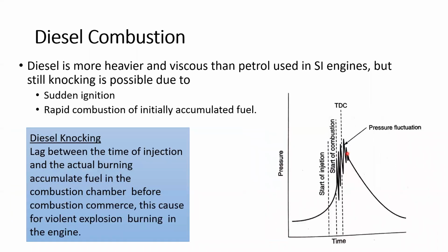In diesel combustion, it is somewhat different. Diesel fuel is viscous and heavier, more like a heavy oil. But still, a diesel engine also knocks. Knock happens through sudden ignition and rapid combustion of the initially accumulated fuel.